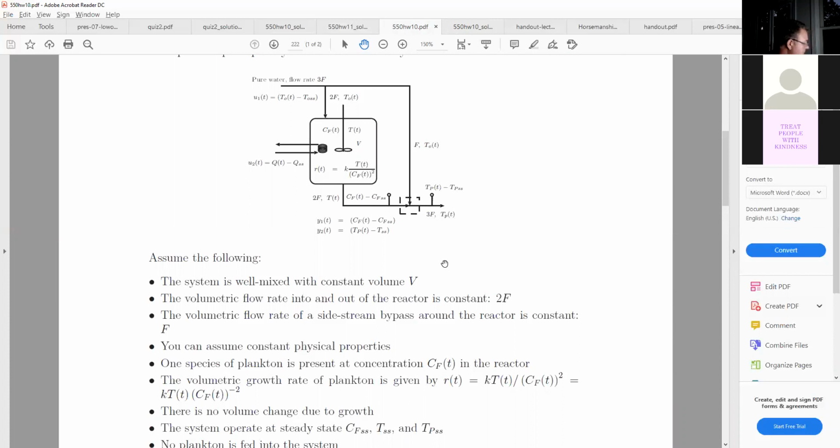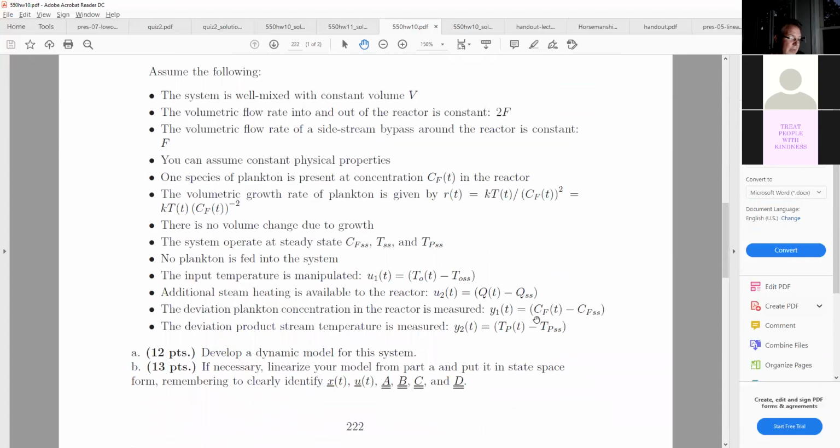If you saw from today in class, a lot of this stuff goes back. This class, like I keep saying, ideally you'd know everything at the same time, but we have to keep growing our knowledge. Today we talked about lead-lag systems, where you have the bypass and the reactor, or the bypass and the tank. You get a different response to a step input. Instead of being a nice exponential curve up, you get a jump and then a curve. And sometimes that's desirable.